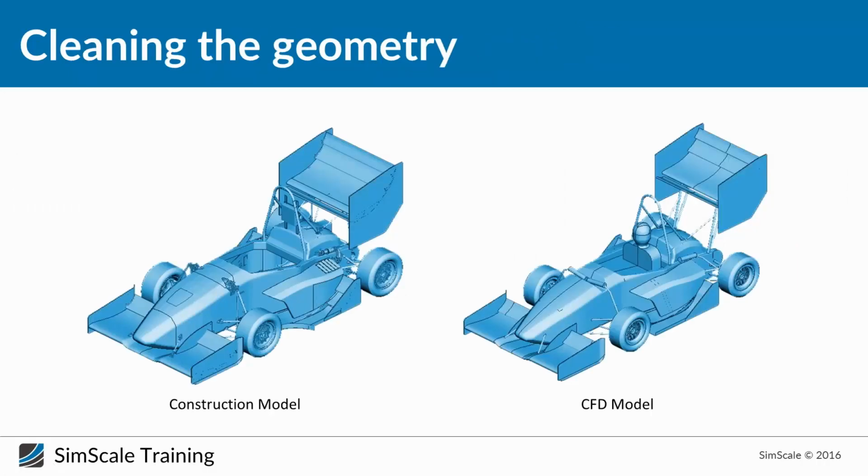Now we have an idea about the problems that we can face in surfaces, in cleanup, or in the pre-processing, because pre-processing is not only meshing, but also cleaning up, meshing, applying boundary layers, applying boundary conditions, and so on. So the second part: once you make sure that you have clean geometry, so that we will not have the kind of problems we have seen before, it's really important to defeature your model.